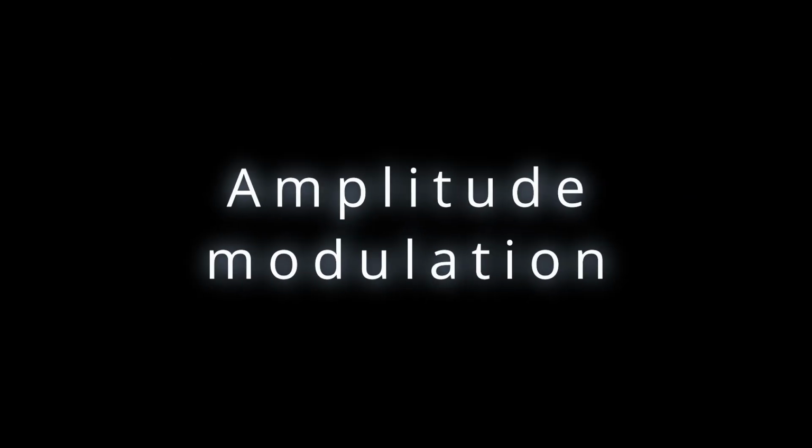That gives us effects like the flanger and the chorus when you modulate the delay period. Something that often just gets called modulation, because they just don't want to get into it, really should be better called amplitude modulation. Or sometimes it's called ring modulation because you use a ring of diodes in order to make it happen if you're building the circuit.